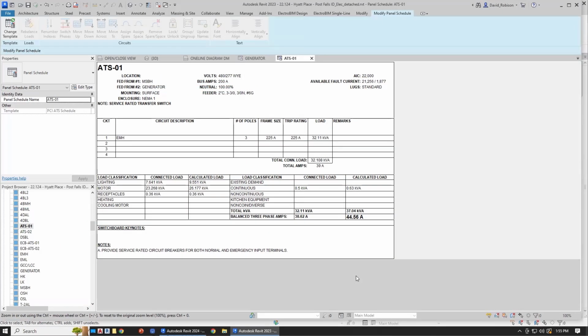Be aware, ATSs are a little bit tricky to model. They're so tricky, in fact, that Autodesk's out-of-the-box ATS is not modeled properly. It only has 1 connection. So if you are trying to do an ATS and you're using the standard one, it's not going to work for you. We have a knowledge base article, and we'll link that in the show notes for anyone watching the recording. So you have that available. It will show you how to create that ATS.